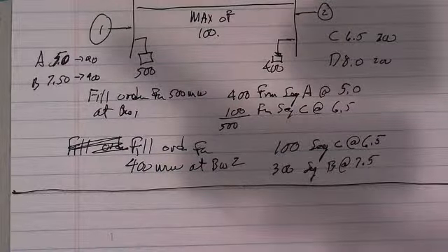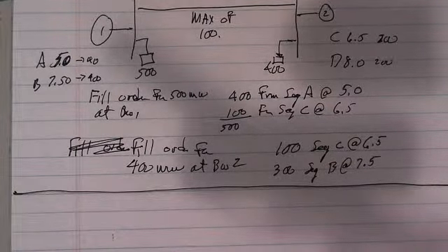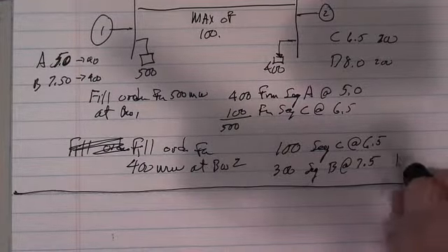And the transmission people are screaming, saying, no, you can't put 200 megawatts on that line. It's 100. And by the way, normally you think of a transmission line as having a maximum that is the same number no matter which direction it's going. If you get into reactive power effects, that could change. But in our example here, it's 100 going 1 to 2 or 2 to 1. So we can't buy it. The answer is no.